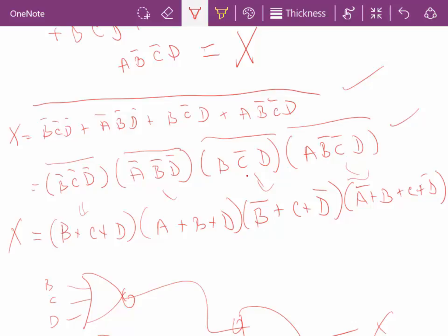Now, I'll be honest that when I used to teach this all the time in my courses before I started dropping it out of my basic digital course because it's not used very much, I could do that without using De Morgan. I would just know to write the inverse automatically when I read out the zeros. I could write it and skip those two steps. I recommend you don't skip steps, because you're not going to do enough of these to really worry about how to skip the steps.